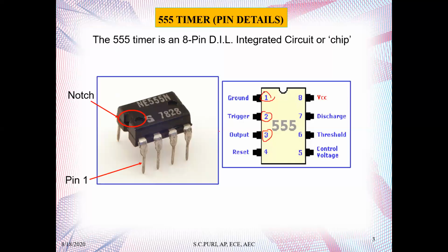Now you see here pin number 4 is the reset pin. This pin is used to reset the internal flip-flop, which we are going to discuss next, and which actually controls the state of the output at pin 3. This is an active low input and is generally connected to logic 1.